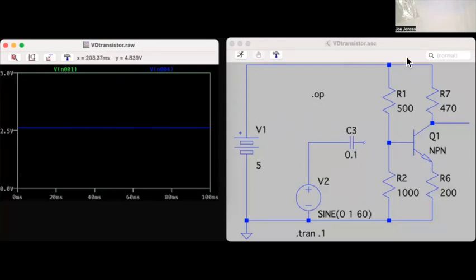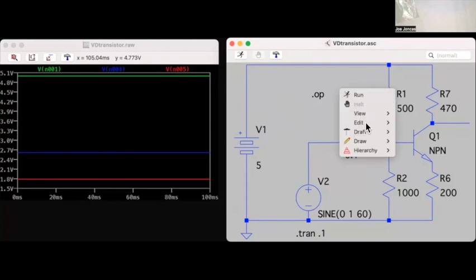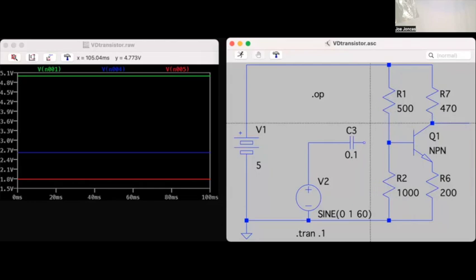So this point right here is 1.8 volts, because of the loss from the NPN. Yeah, because of the low drop in current, it's showing 9/10 of a volt drop. You can usually figure about 0.7 volts. But now what I'm going to do is I'm going to come over here, draw wires, and I'm going to connect this signal right here.